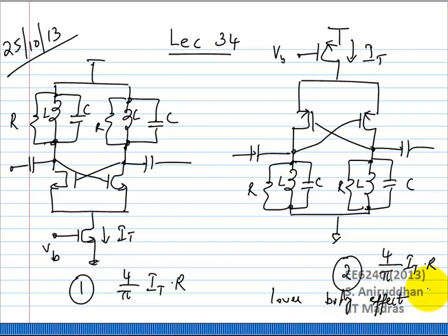Okay, let us go back to this thing, right? Let us say this was GMP and this was GMN. I am going to make this GMP equal to GMN. So can you think of what will happen when I try to do this? I am making the PMOS 2 to 3 times larger. What effect do you think it will have on some other characteristic of the oscillator? Yeah, parasitic cap, right? The minute you make the PMOS 3 times larger, it will have 3 times larger parasitic cap.